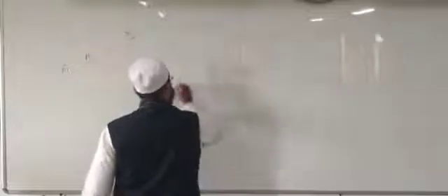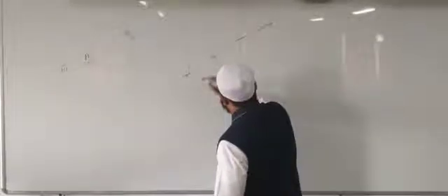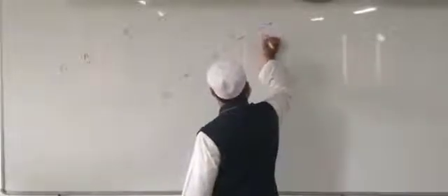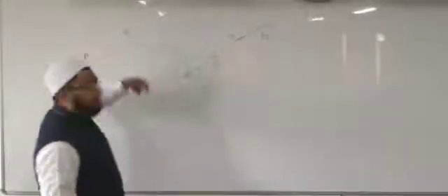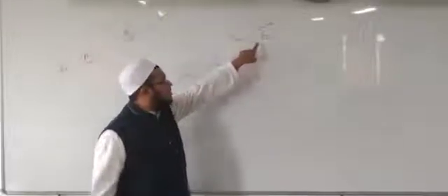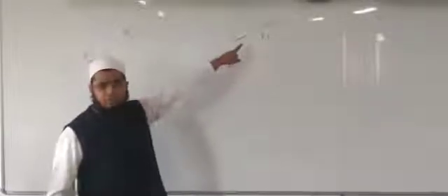We will see the principle of superposition in this figure. Assume that this point is B, and I will add and subtract two forces of the same magnitude but opposite in direction at point B. The total overall force system is not changing because force F1 acting at B is cancelled by force F1 of opposite direction.